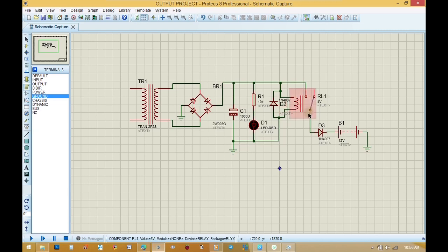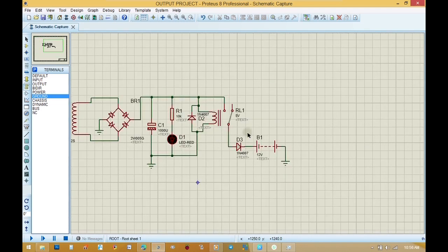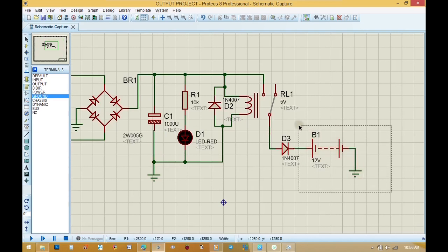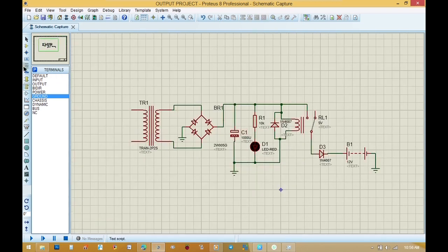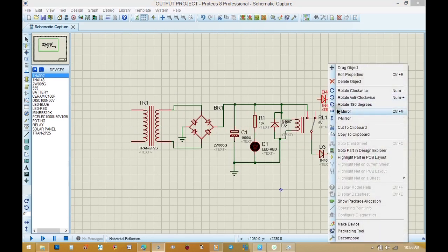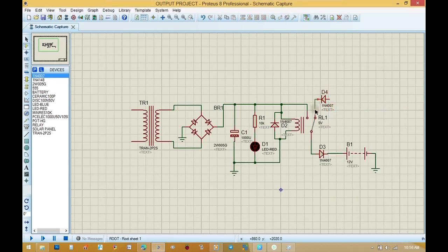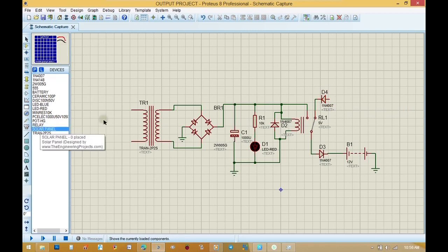The DC that we got from the rectified stage from the power supply is connected to the normally open of the relay, so that when NEPA brings light, it will transfer the battery. You can see the battery is being connected to, what is it called, the movable contact of the relay, positive terminal to the load, then the other one to the ground for the movable contact.